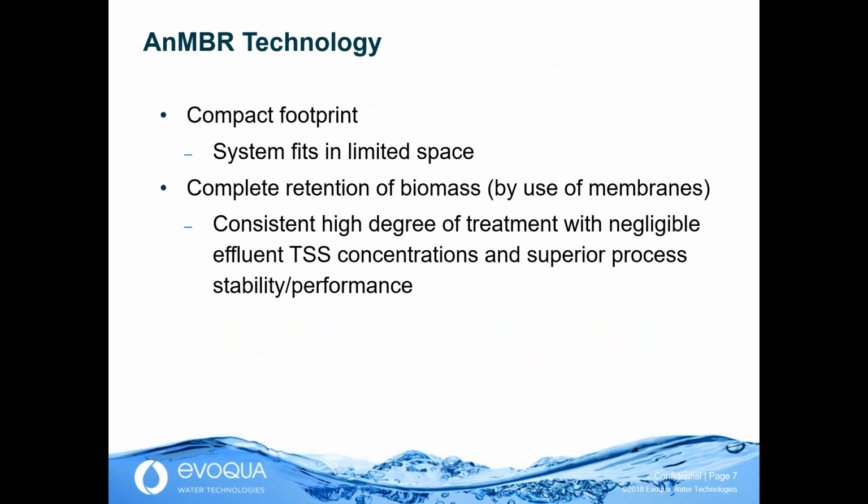A few other benefits of the anaerobic MBR is that they have a very compact footprint. They can fit in very small spaces when required. The reason the systems can be compact is because the membranes retain all the biomass in the system, and thus we retain a high inventory of active biomass, and there's no fear of losing biomass since the membranes provide that absolute barrier.